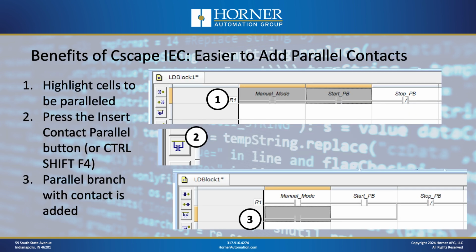Okay, so another point on John's spreadsheet when it comes to ladder editing, he feels it's a lot easier to add parallel contacts in ladder. Much easier because you have the one icon, you just keep clicking and you're adding one parallel contact after another, whereas in advanced ladder, you have to use the little vertical horizontal shunt tool to piece your logic together. Agreed. And how often have we not done the left side power rail properly and gotten an error? Good point. Good point with that.